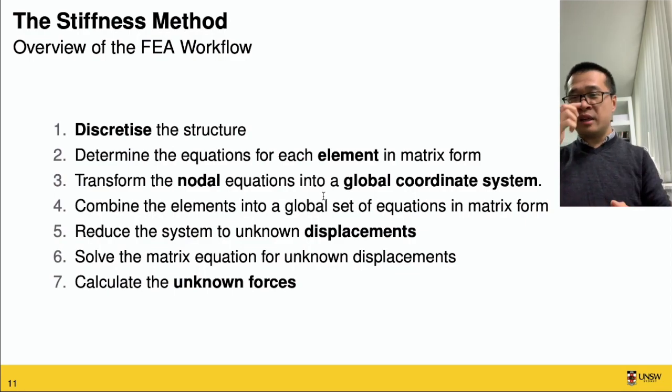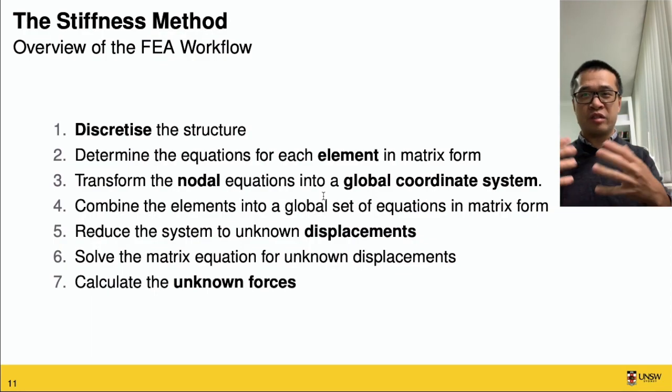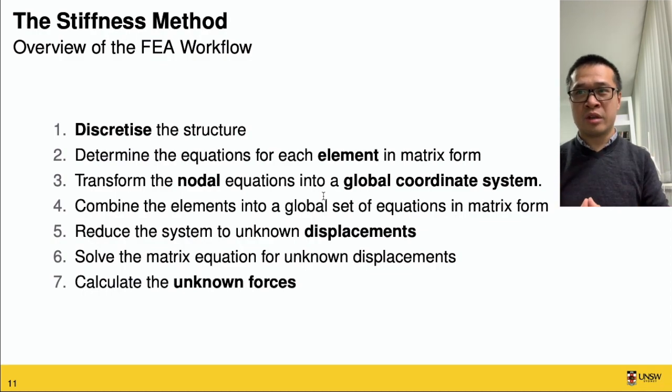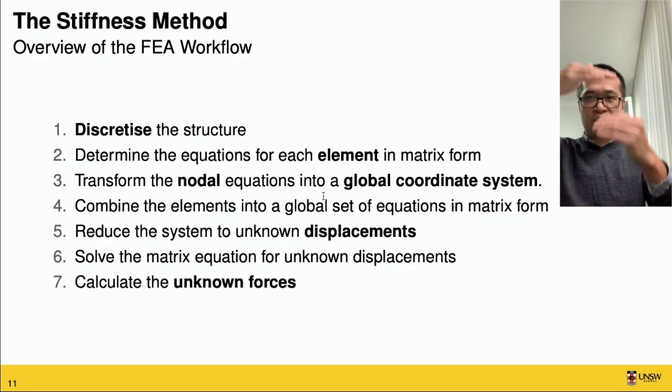And once you've done that, you have all the equations in hand, and you put them into what we call a matrix. If you did your first year mathematics, we all know what a matrix is. In very simple words, that matrix looks like Hooke's law, where your F now becomes a long vector of all the forces on each node.